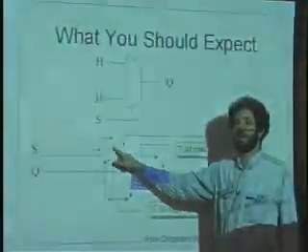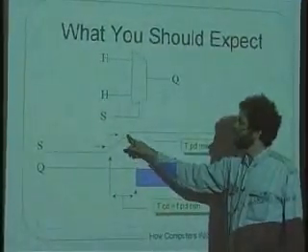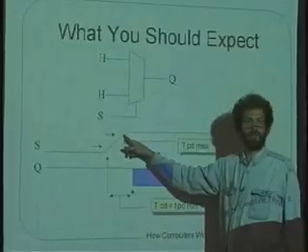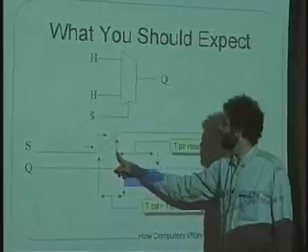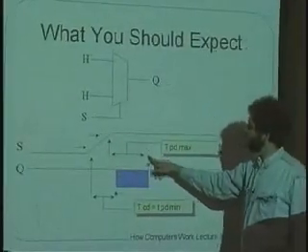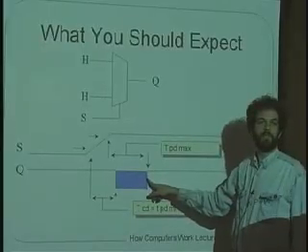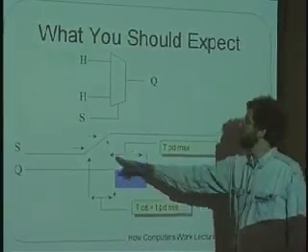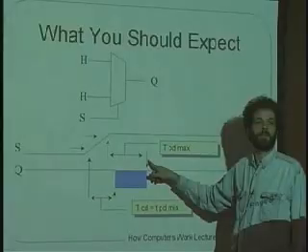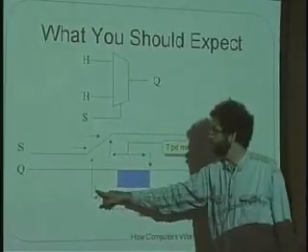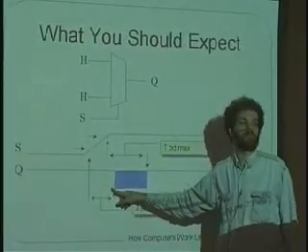And so we measure TPD max, or TPD, by saying when does S, if it takes some time to go from low to high, finally become the valid new value here, and when does it finally come out with the valid value on the output here. And this is the longest that could take. And this time here would be the shortest that the contamination could happen.